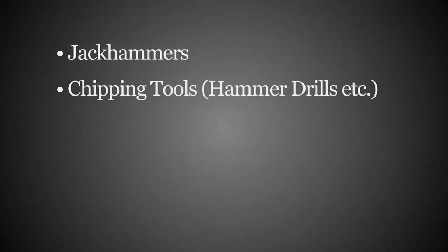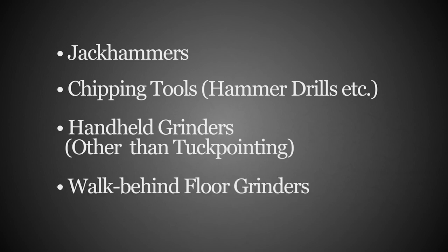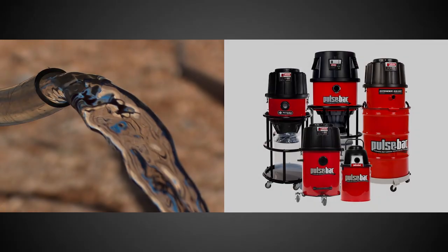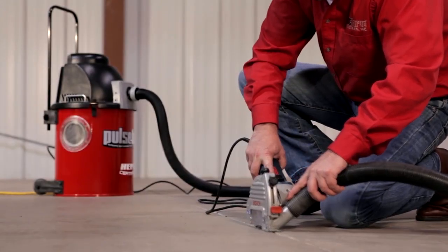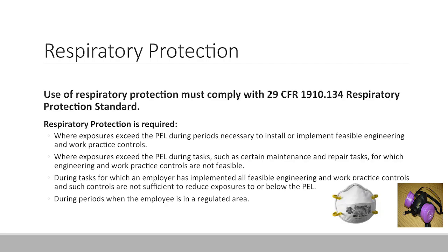Jackhammers, chipping hammers, handheld grinders, walk-behind floor grinders. You have the option of using water or a dust collection system with these tools. When using a dust collection system, the filter must be 99% or greater efficiency with a filter cleaning mechanism. Some other requirements may include respiratory protection.